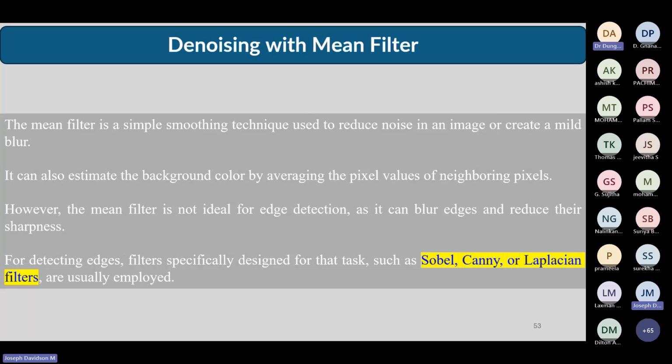Now, coming back to the mean filter, I said that it takes the mean of all the neighboring pixel magnitudes and replaces the pixel. Now unfortunately, let us say you have gone to an edge. At the edge also, there is a huge magnitude.